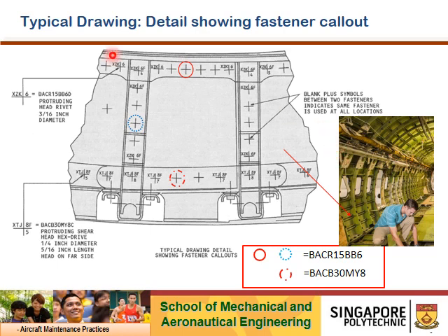So if this is the aircraft drawing and you are trained, you should know that there's a XZK, X-ray Zulu Kilo. So it tells me that if I go back to the manufacturer reference code page or documentation, XZK, it tells me that it's a BACR15BB60R. This part number is slightly different, as I mentioned earlier.